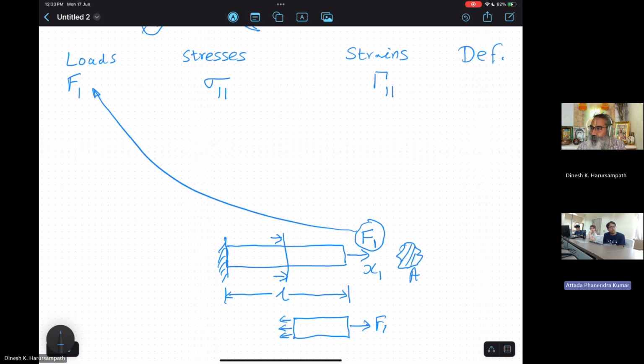It would be 2,2, because you're having the Poisson's ratio, where as you're stretching it, you're causing another strain. Absolutely, absolutely. So gamma 2,1 is possible, but only when you have composites of a particular layup. The couplings might be there because of which gamma 2,1 might be there.